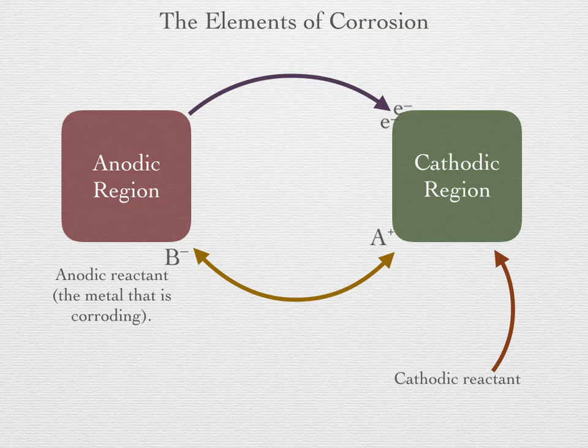The anode and cathode regions may be entirely separate and macroscopic in size, or they may be very local to each other on a heterogeneous metal surface. Tiny microcells can arise due to differences in phases in the metal resulting from different heat treatments or from welding. Bending a metal introduces stress that can alter these conditions. There can be natural chemical barriers, such as an oxide layer, or artificial ones, such as paint.